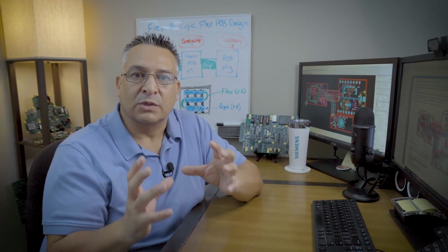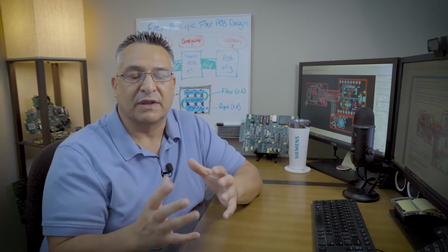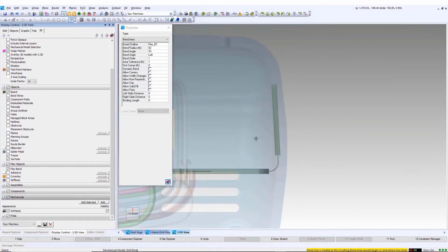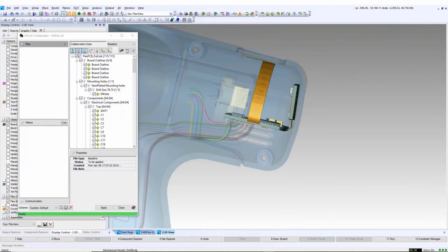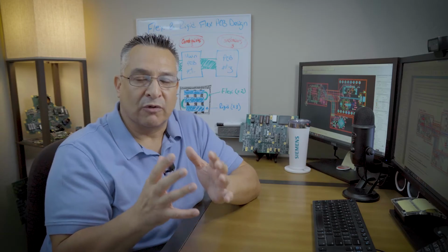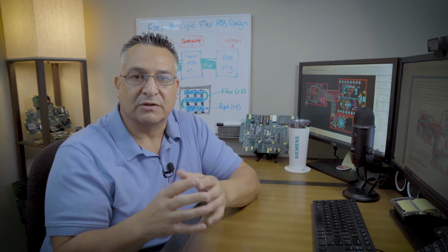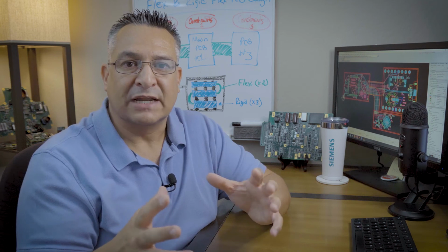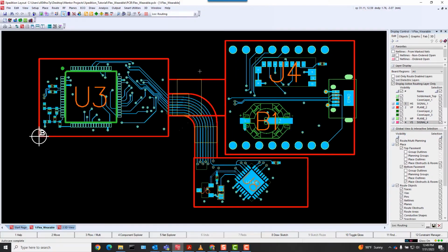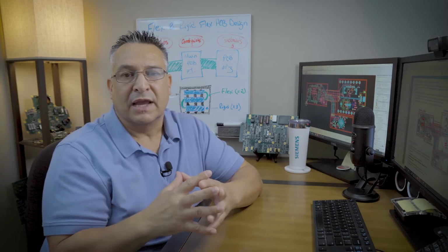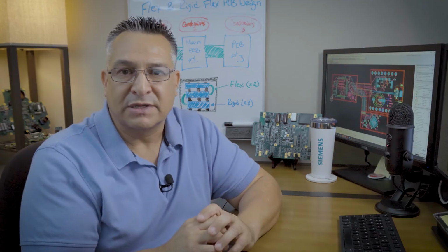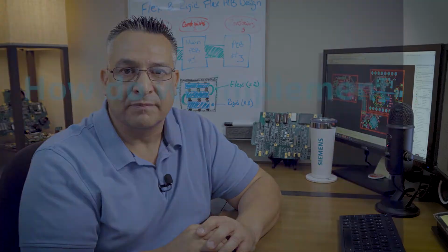The reason why you would implement or enable flex and rigid flex in the design is due to a limited space requirement within an enclosure. You may have multiple boards that need to fit in there, but there's limited room to add board-to-board connectors or cables. Designing for physical and mechanical constraints within a specified design envelope with limited space enables the opportunity to eliminate board-to-board connectors or extra cables, and it allows for a cleaner transition for signals to go from one CCA to another. Therefore, it increases the potential for signal quality.